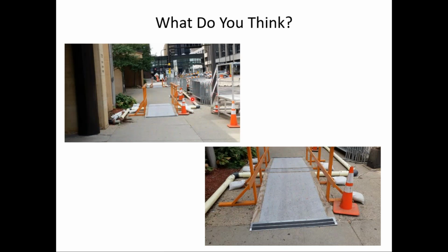material and the plumbing and the other stuff that's going on there. And that, again, is not so much an accessibility issue as it is a safety and probably risk management issue, because if someone would get in there and get injured, then you have a lawsuit against the municipality, against the contractor. And so I think with just a little bit of effort and some channelizers here or detectable edging, they could have kind of eliminated those particular issues.